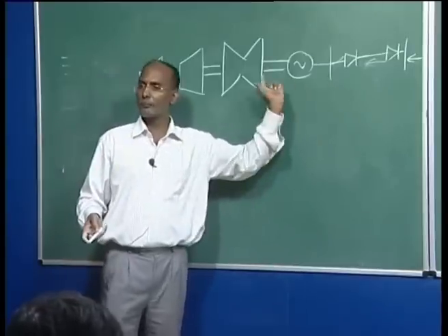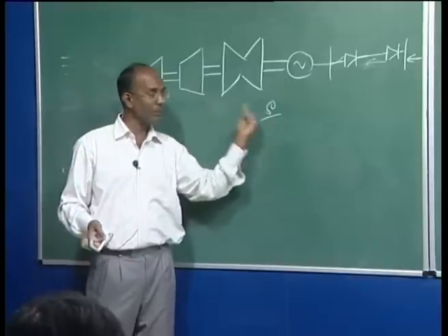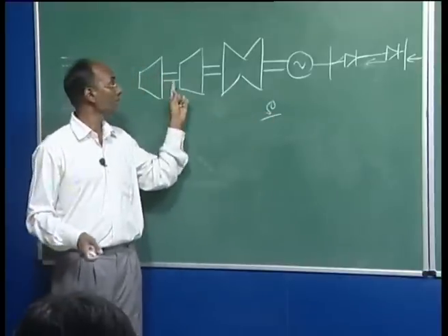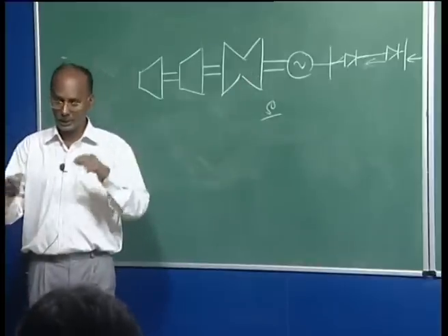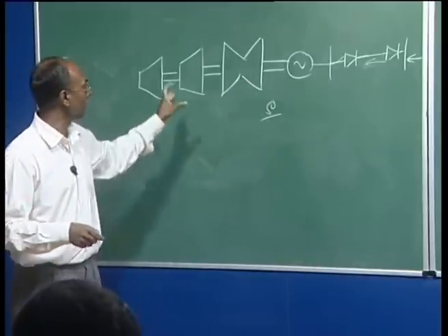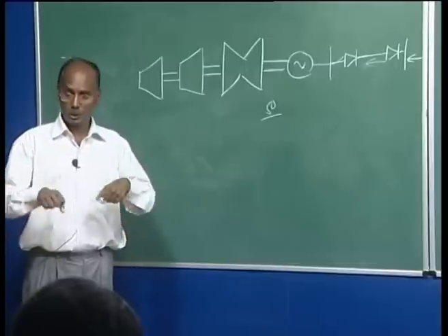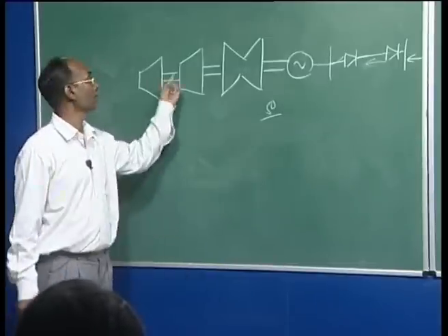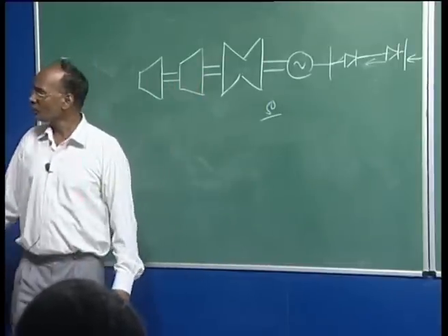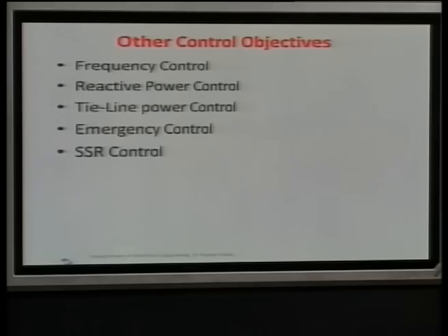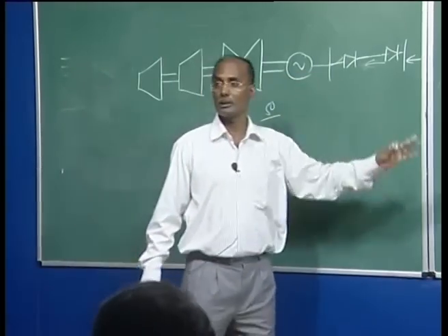That will not affect at all. But if a frequency less than 50 hertz enters here, then the critical frequency may synchronize and match, and then huge torsional oscillation or torsional torque will be developed, and this shaft may be broken. So this can also be done if it is used in this way for some specific purpose.